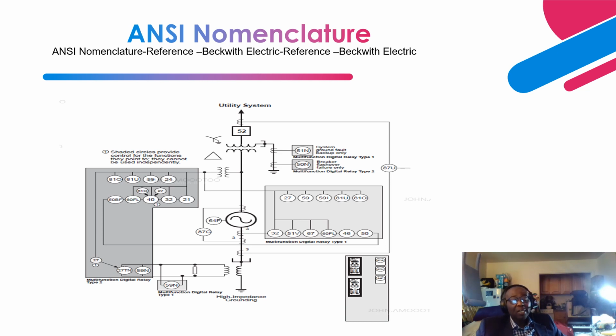So you need another relay to complement that protection. That is when the 27TN covers the remaining 5%. In fact, they set it in such a way that it overlaps. It covers about the last 10% of the neutral of the generator by creating an overlapping zone.